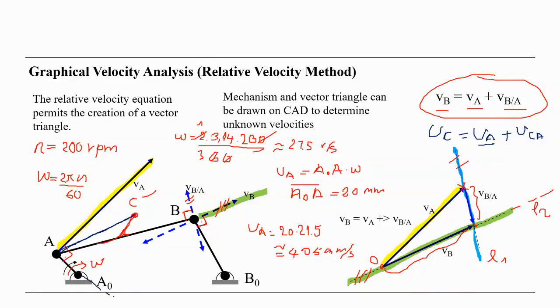If we extend this line and this line here, they are crossing somewhere here, and we have the instantaneous turning center somewhere here, and then the point C is also turning at that moment, at this instant, around this instant center, and the velocity must be perpendicular to that.